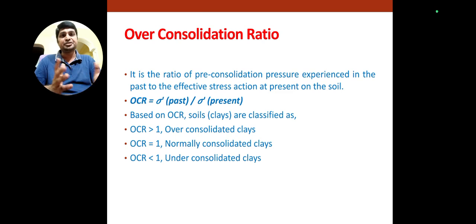Here are some ratios we observe, that is the over-consolidation ratio: the ratio between the pre-consolidation pressure experienced in the past to the effective stress acting at present on the soil.